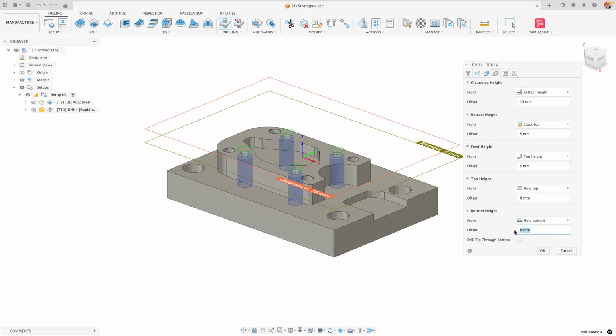I can use model aware information in these settings. Now these are often, for holes at least, under an option for auto. So if I type in auto, you can see a lot of information about the hole that's being pulled through. Now in this case, I want auto thread depth, and I could say that I want this offset by 0.1, 10% of the depth of the entire hole.